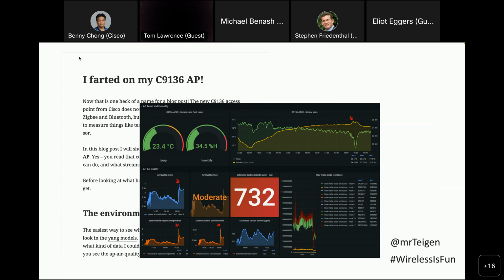There's about a 5 second delay between the time the sensors sensed the poor quality of air and when the readings actually showed. In this case, he took a screenshot. Temperature went up, humidity went up, and then it dropped quickly because, you'll find in the blog, I think he opened some windows, so the humidity and the particulates, or the TVOC level counted in parts per million in the air, was reduced, and hence the levels went down. I thought that was interesting. Our QA folks didn't test it this way, but I'm glad this person wrote the blog about it because it definitely showed how sensitive the sensors actually are.